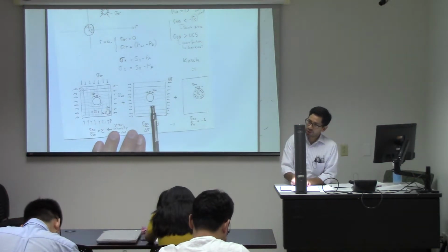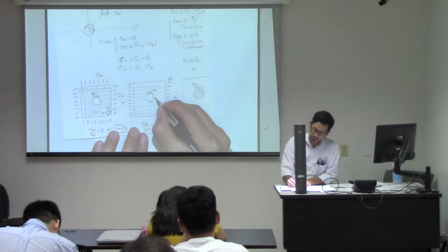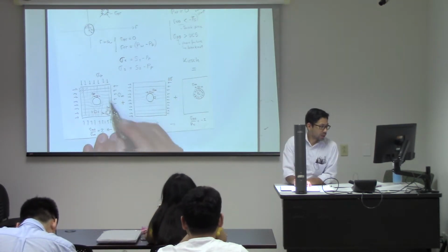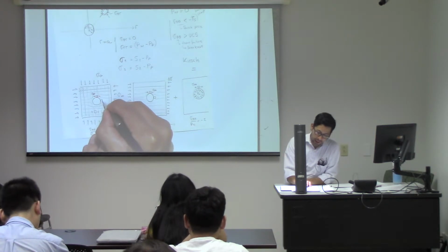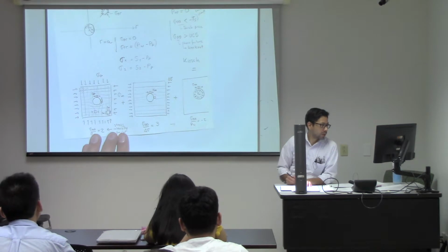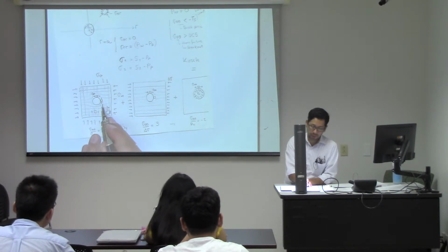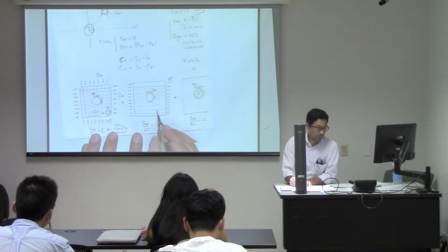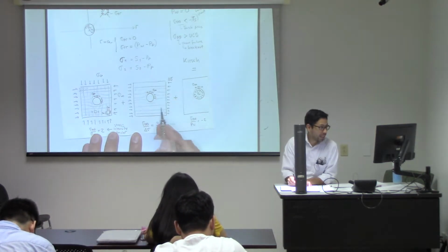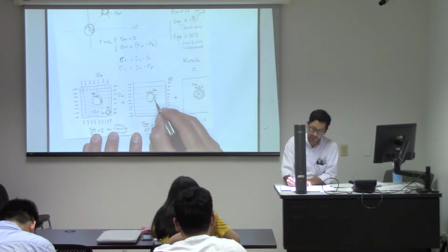If you solve this equation here too, you will see that in this case, so if I took another element, say over here, it will also be compression. All around, in this example, the wellbore, you have compression. But if you come to this place, because of the direction of the stresses, you will find out that now here you have tension.